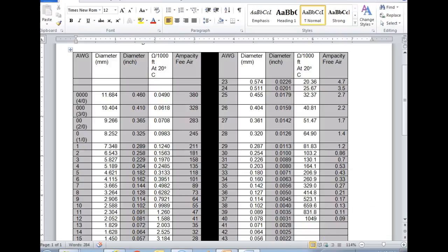But it has 2.52 ohms per thousand feet. They rate it at 32 amps, but it has 2.525 ohms per 1,000 feet, or let's just say 2.5 ohms per 1,000 feet. This is copper. So if I ran it 2,000 feet, then that's going to be 5 ohms, right? If I tried to put 10 amps through 5 ohms, it's going to drop 50 volts.